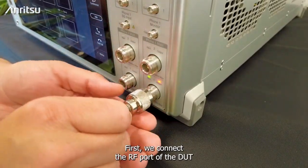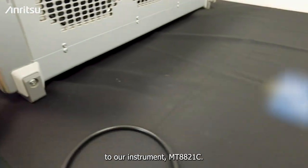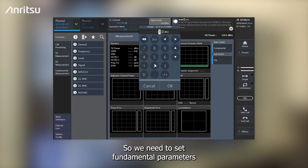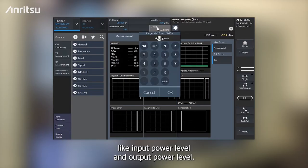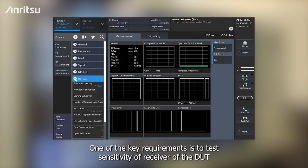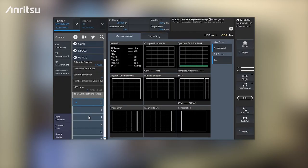So now we are going to look at the step-by-step process of the measurement. First, we connect the RF port of the DUT to our instrument MT8821C. Next step is the parameterization of the network. So we need to set fundamental parameters like input power level and output power level. One of the key requirements is to test the sensitivity of the receiver of the DUT by emulating a low power received signal. By applying repetitions, we can go as low as minus